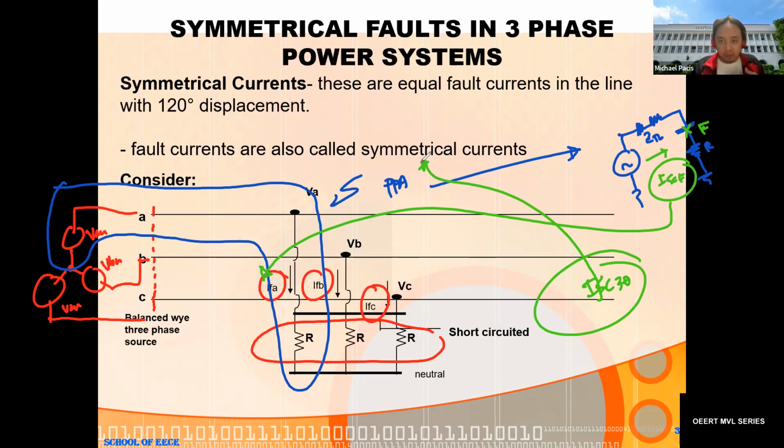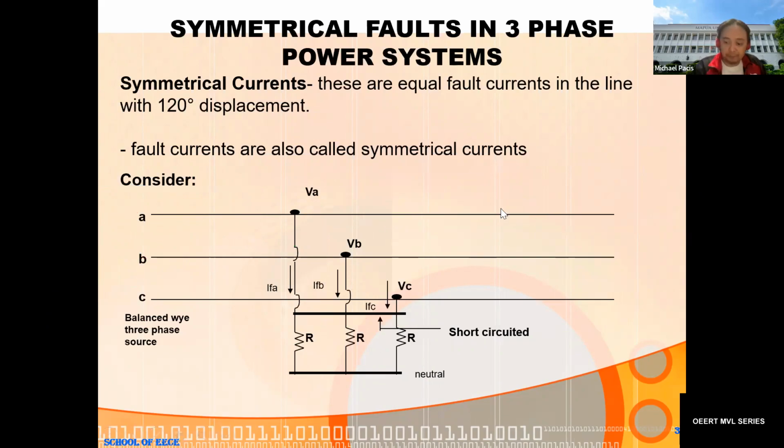If you have a power system, it's very important that you know the modeling techniques. From the modeling techniques, you can have the positive sequence network. From the positive sequence network, or the per unit equivalent circuit, what you will do is get the short circuit current, and from there you will use a little bit of circuit analysis using Thevenin's theorem. Okay. Now, for this, we can clear this up so that we can move forward.